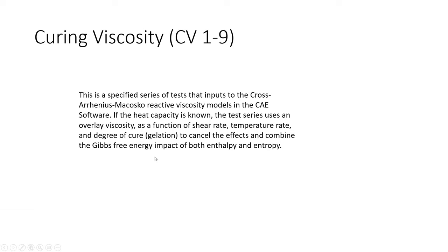The injection speed was set so fast, I think I might have damaged the equipment. I don't recommend it. But when we did that, we were able to inject LSR silicone into a cold mold. Cooling water was actually on the tool. It was a plastic mold, and the temperature was about 38 degrees Fahrenheit.